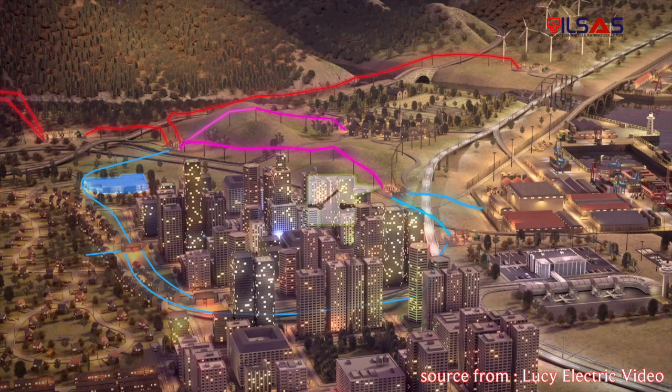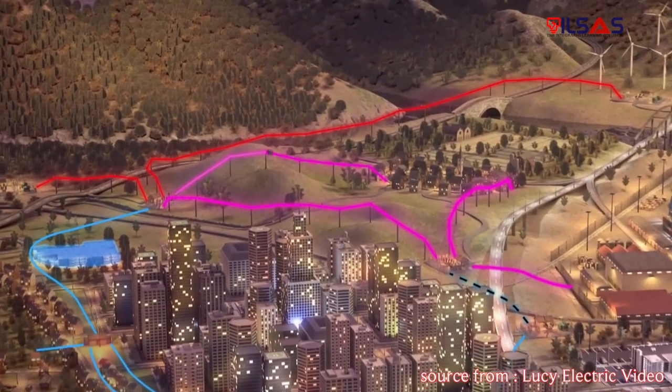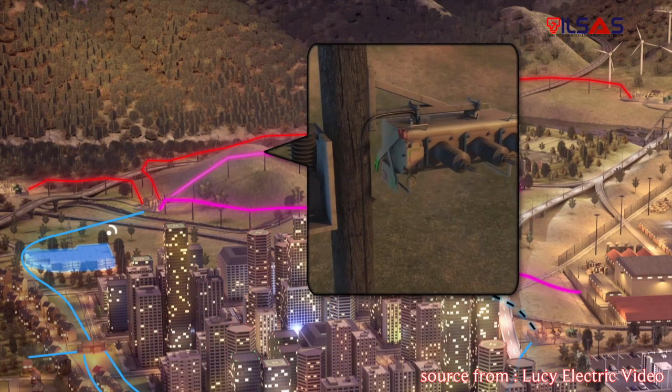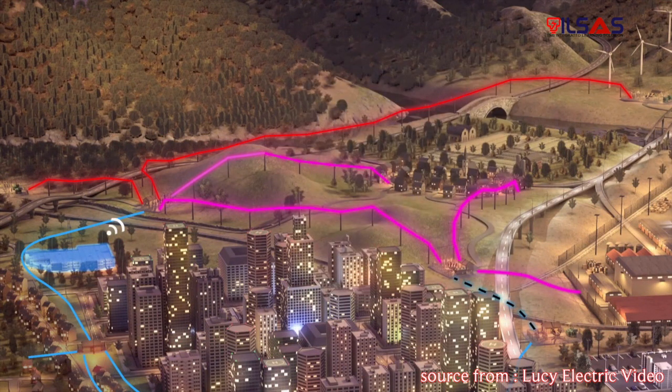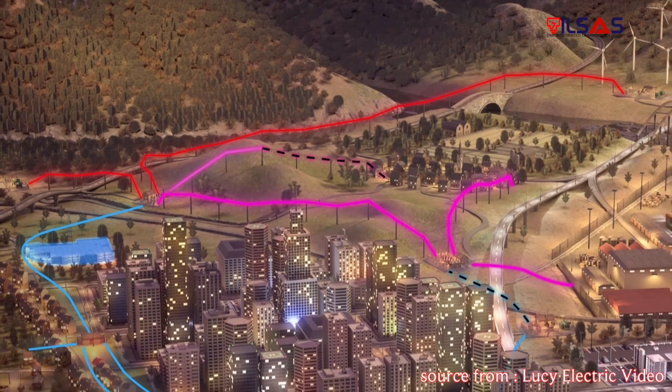The operator can now close the incoming switch to substation 2, reinstating the original supply route. The backfeed from substation 3 is no longer required, and so the Scada operator can open its outgoing switch. With the load removed from the lower side of the network, the rural community outgoing switch from substation 2 is closed, creating a parallel circuit for the area. The final step for the Scada operator is to reopen the GX switch to disable the backfeed to the rural community, restoring the standard operation of the whole network.